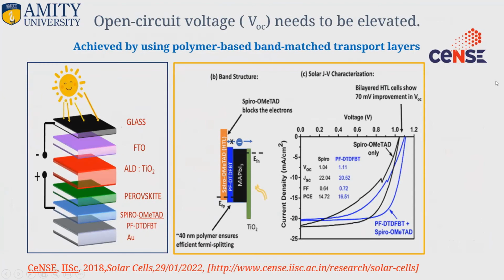Okay. Efficiency of a single material solar cell is limited by the SQL, the Shockley-Queisser limit. The SQL of perovskite and silicon is around 25% and 30% respectively, and one way to exceed this limit is to integrate different absorber materials onto the same device, forming a tandem cell. Given the band gap of perovskite and silicon, the tandem cell can theoretically have an efficiency of more than 40%, and even the realization of a practical 30% efficient solar cell would have a tremendous impact on cost and viability of the technology. Next, please.